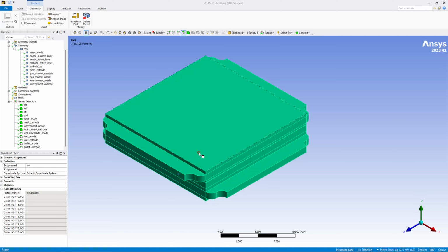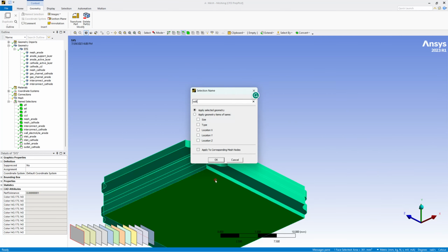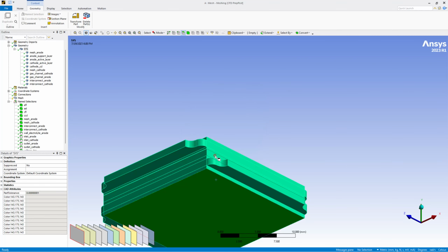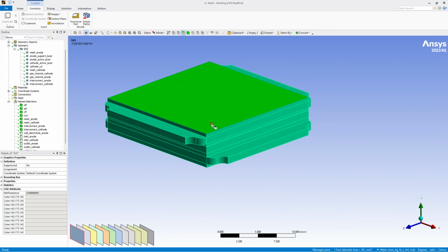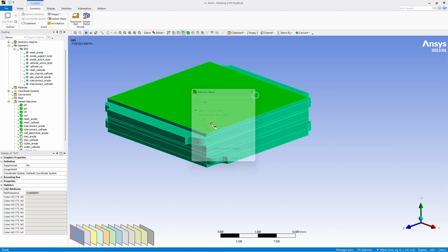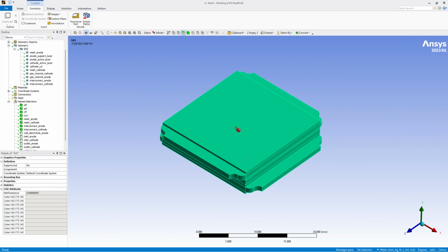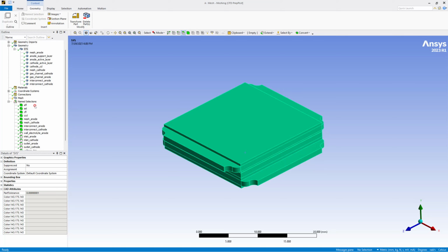The voltage tab is on the anode side. We model the geometry with cathode on the top side. So on the top is the current tab, and voltage tab is on the anode side, at the bottom. This is the voltage tab surface, and this here is the current tab. Okay. Now with this we have finished the name selection, and now we need to start with the meshing.